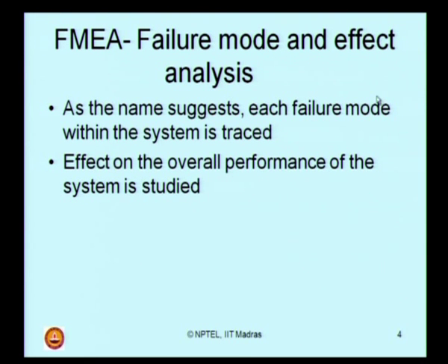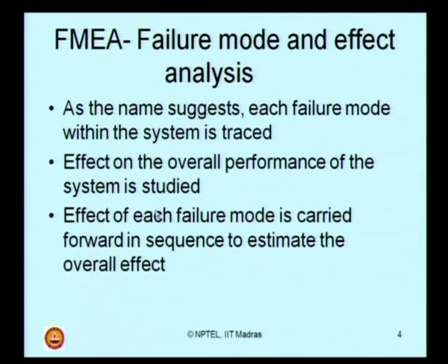So you identify a failure mode for a given system, usually a mechanical or electrical system. For the identified failure mode, what is its effect on the overall performance of the system, that is what you analyze. The effect of each failure mode is then carried forward in a sequence to estimate the overall effect.